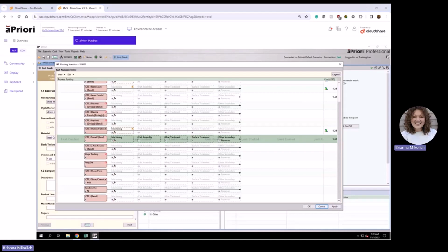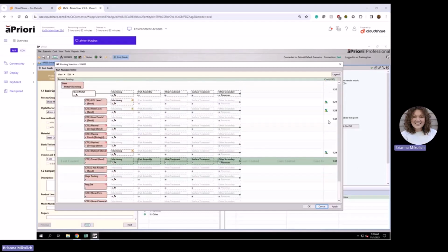I know these are feasible because they have a cost over in the right-hand cost column and no visible errors. That's opposed to CO2 laser, fiber laser, and water jet, as they do have costs, but they also have errors. And if I hover over that fiber laser that we discussed before, we can see in the tooltip that it cannot manufacture the form.